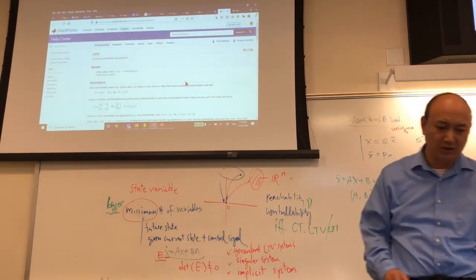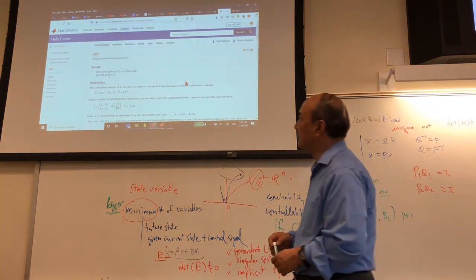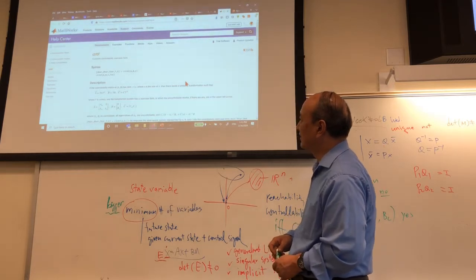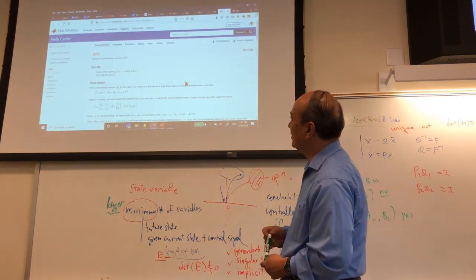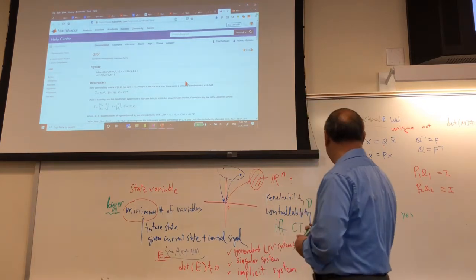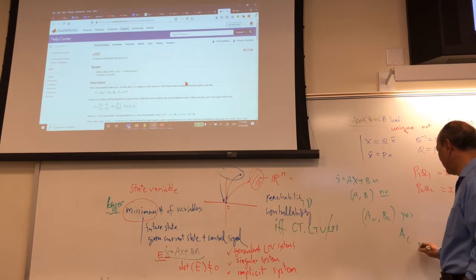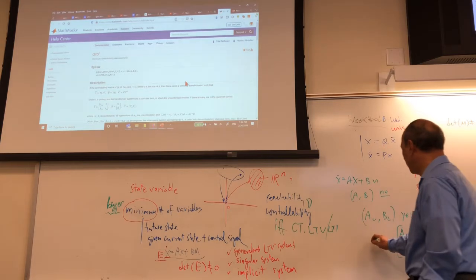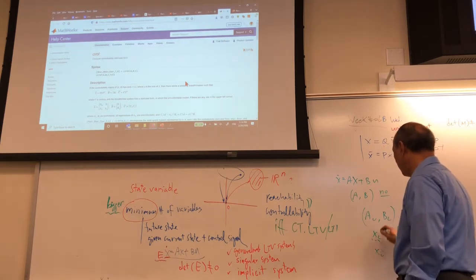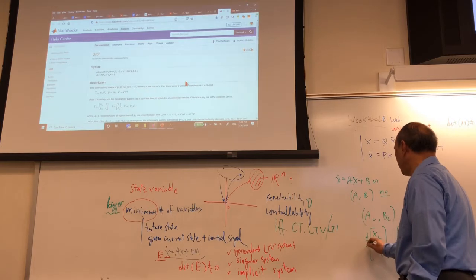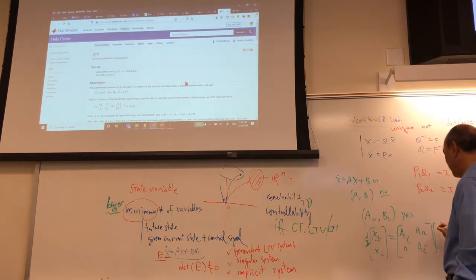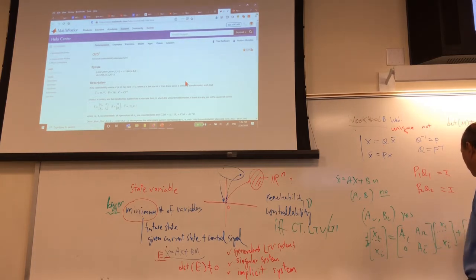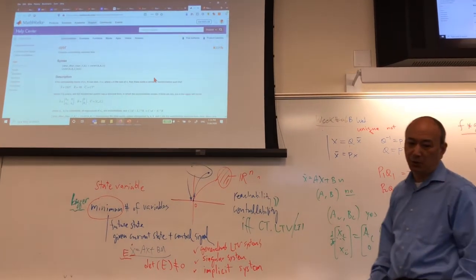There's a function, ctrbf, that is going to give you the controllability staircase form. That is exactly the A-bar with the block 0, A12, and then x-c-bar, and d/dt of x-bar equals this one, x-c-bar plus B1, B2.